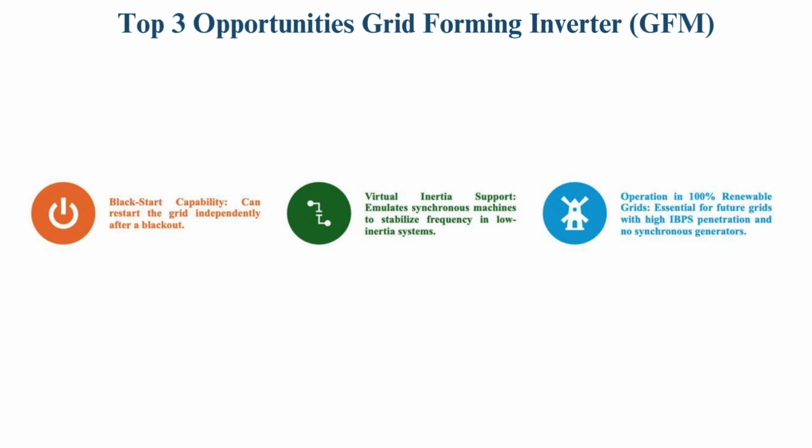Top 3 GFM opportunities. 1. Can restart the grid independently after a blackout, black start. 2. Provides virtual inertia to stabilize low inertia systems. 3. Enables 100% renewable grids without relying on synchronous generators.